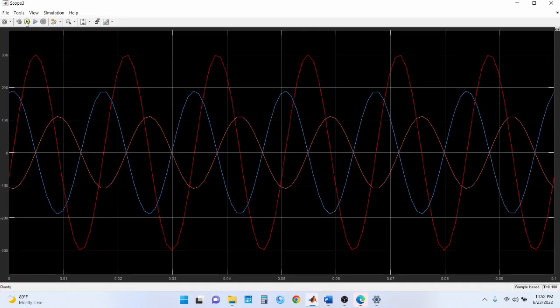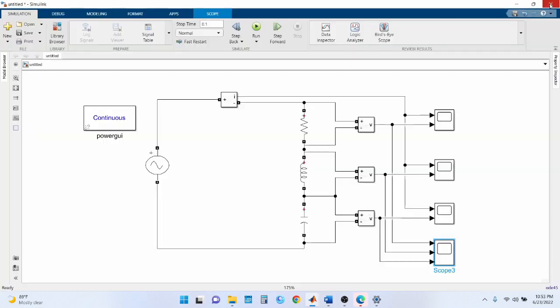All right, so you have this wave, beautiful wave, right? So you can see that each of them are partially apart. Then in the case of resistor, it's quite exactly in phase with the current, and when it's inductive, the voltage is actually leading the current, and when it's capacitive, it's actually lagging behind with respect to the waveform of the current. So this is actually what you're going to examine in this lab, and that's it.